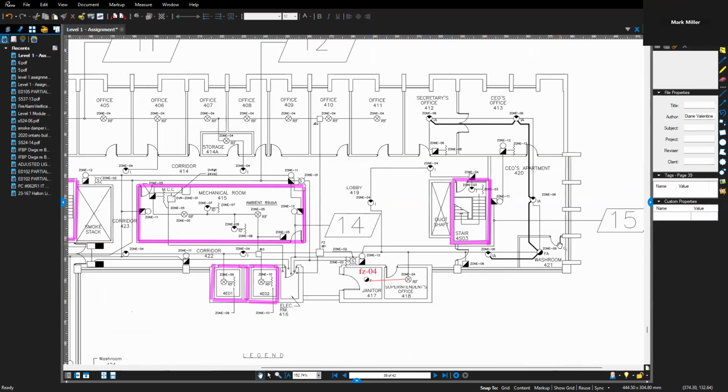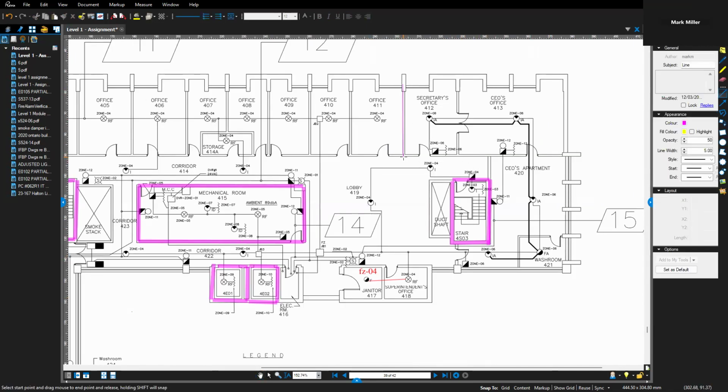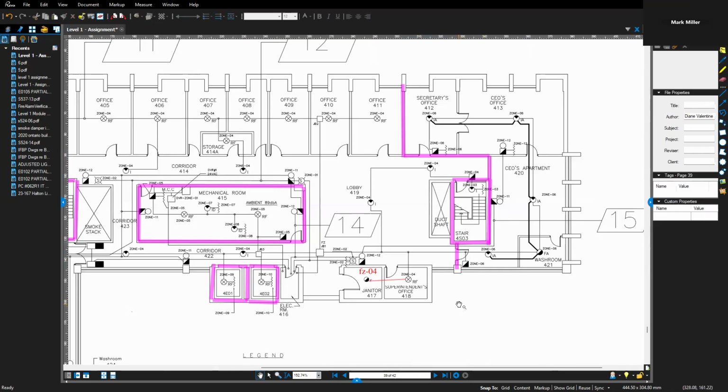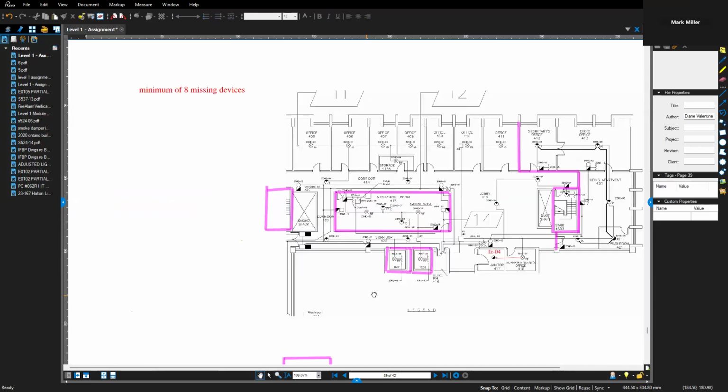Now, looking over here, I'm noticing these devices are on Fire Zone 6, so that looks like a fire separation as well. Right? So I'm going to draw that in as a fire separation, again, just to make it a little bit easier to tell what's going on. You do have 2 copies of this. You can have a rough copy and a good copy, so that you can scribble in notes and everything as needed as you go.